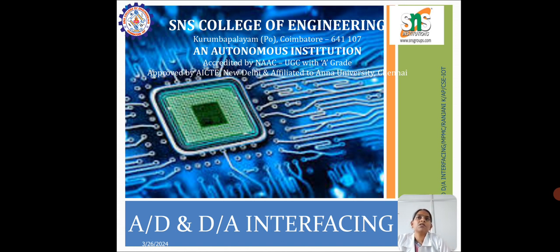The specification for an A to D converter is very similar to the D to A converter. The resolution of an A to D converter refers to the number of bits in the output binary word. An 8-bit converter, for example, has a resolution of 1 part in 256. The accuracy and linearity specifications have the same meaning for an A to D converter as they do for a D to A converter.